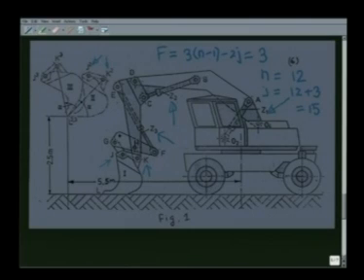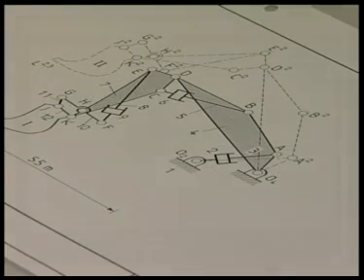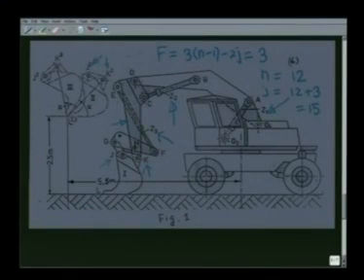Second thing to note is that there is a very high order link which is connecting at C, D, E, H and K. That means this particular link has 5 revolute pairs in it, and it is a link of 5th order. So, we will show how we can use the tracing paper very conveniently to locate the revolute pairs in this kind of higher order link. Let me now solve this problem: when J and K move to J2 and K2 respectively, how can you locate all the other moving revolute pairs, that is at B, C, D, F, H and G and A.